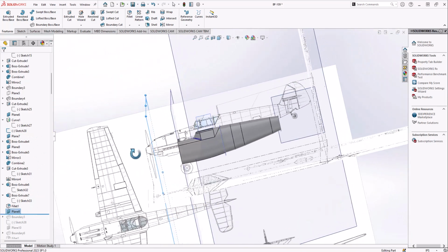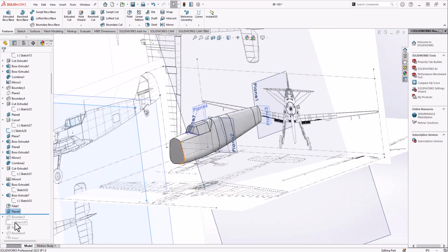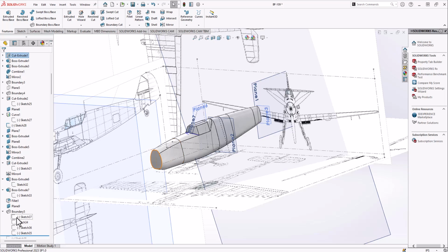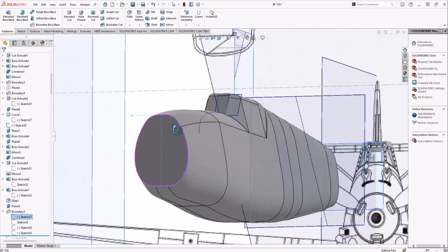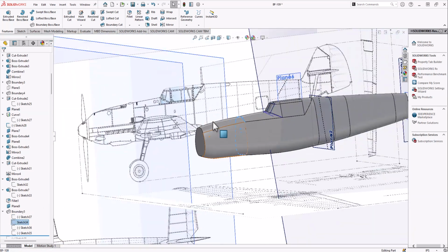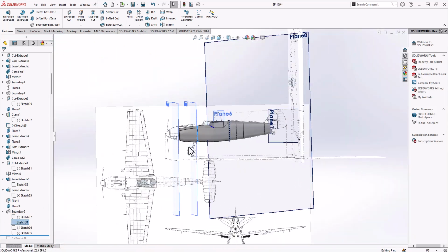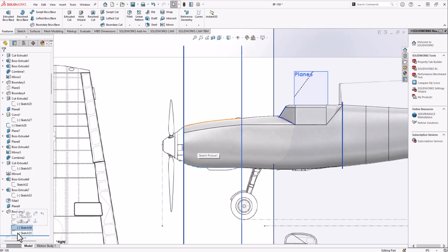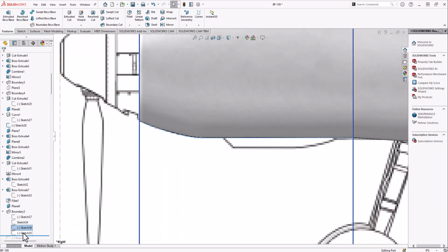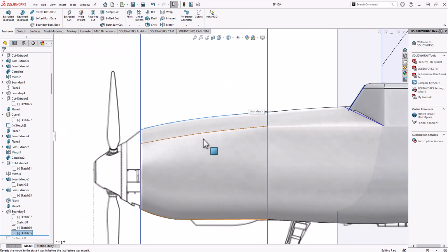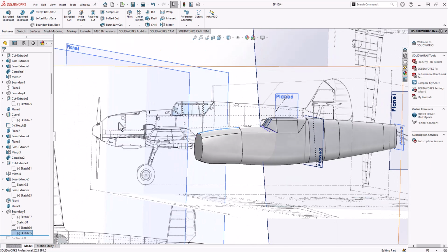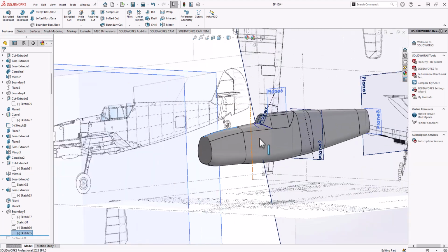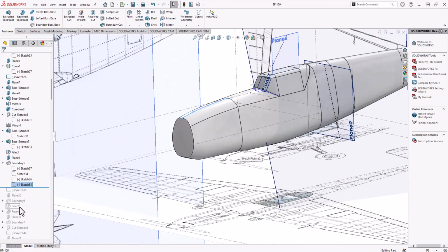Let's see, this plane is up here, so now I'm doing the nose section of the aircraft. So again, a boundary boss extrude, and now I've got this more circular approaching region. I've got this back region, and then again I've got this top or bottom, I suppose, here, and top contours that are the guide curves that are just tracing the side view schematic.